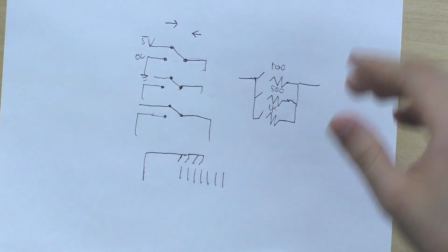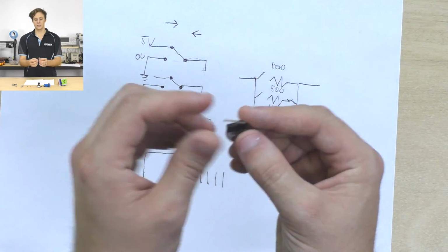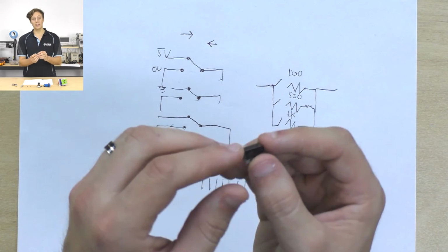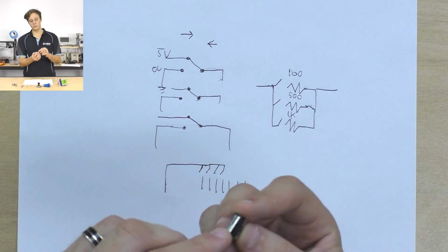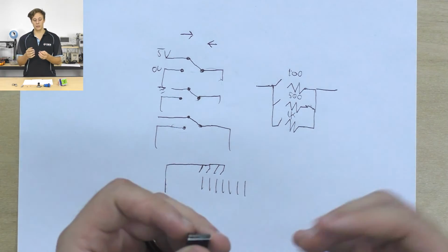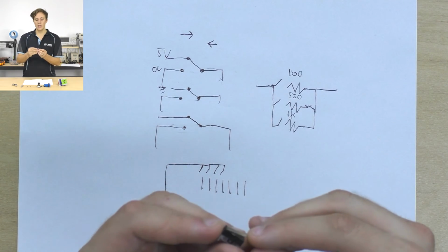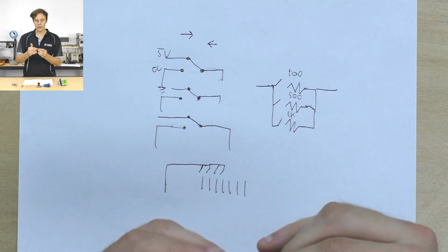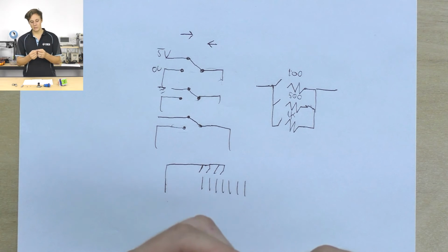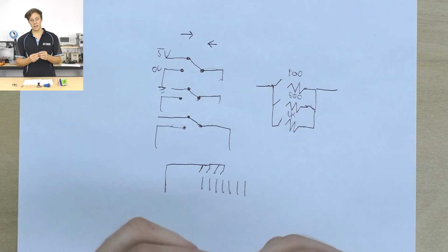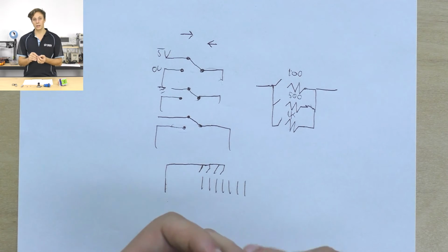So there are a few different types of switches, and the rest of them really are variations. So, different mechanical actuators. Here we've got what's called a lever micro switch. It's designed for incredibly low force to be applied, hence the lever. Lever action creates an increase in torque from the mechanical input to where the switch is. And it's designed for really small, fine applications where you just want a really small force to trigger that. And the 3 pins gives it away that it is going to be a single pole double throw switch. I can see on, and C, so probably common.